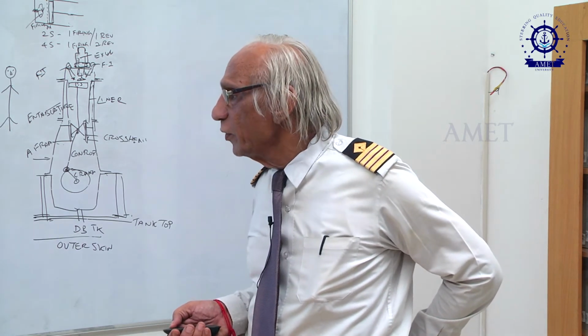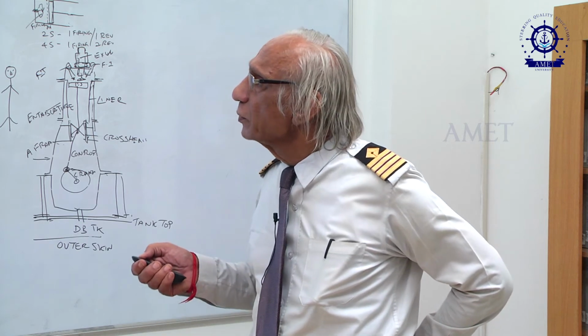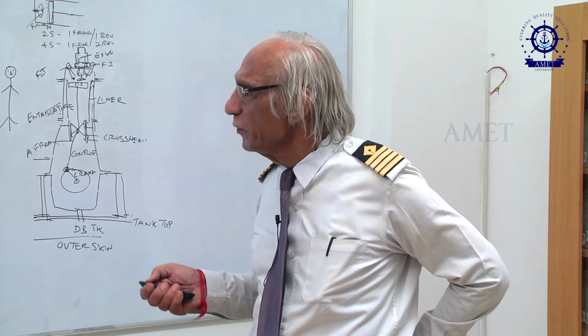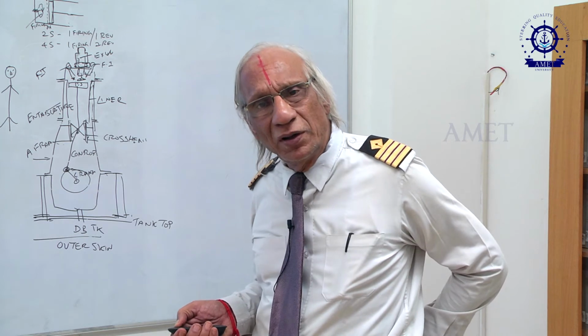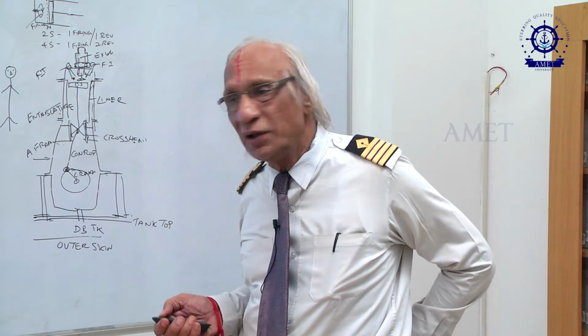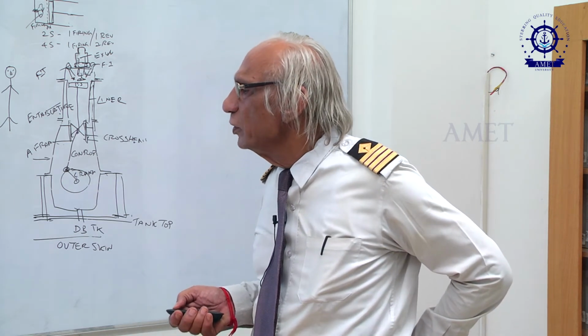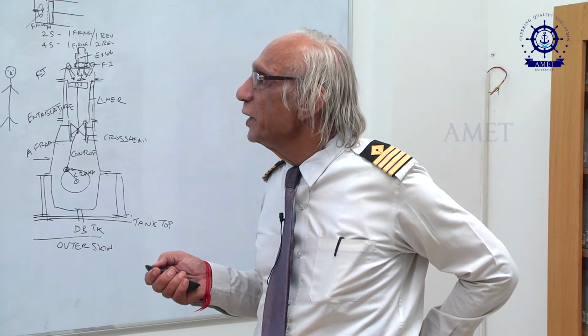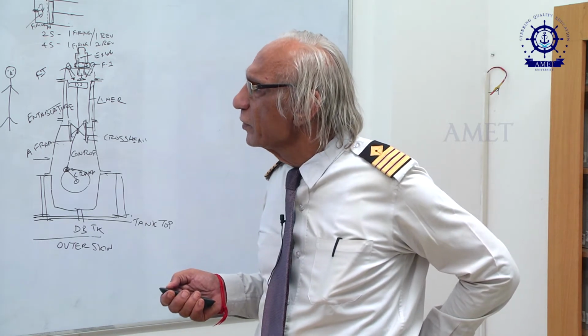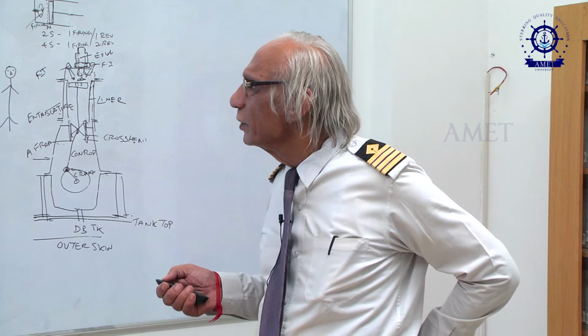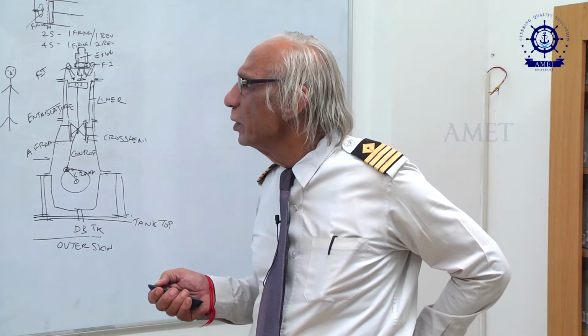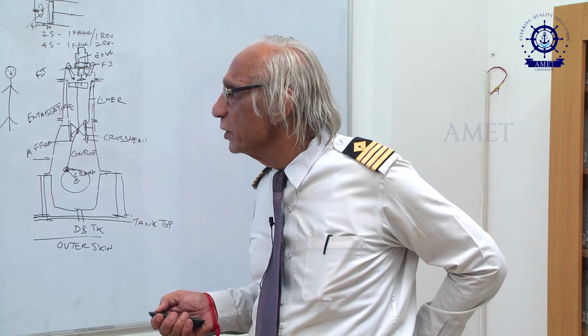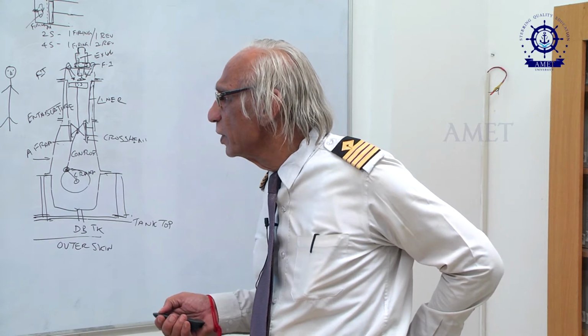Because we are talking about flexibility, the material of this bed plate, the longitudinal girder, which is box shape, should be mild steel, low carbon steel. It will have some amount of ductility and flexibility. Whereas these two longitudinal girders are connected across by a transverse girder. This is called the transverse girders.